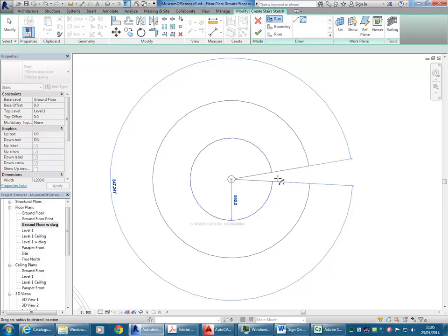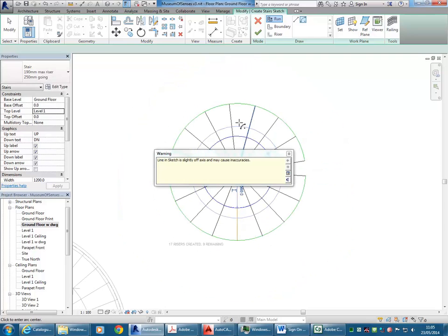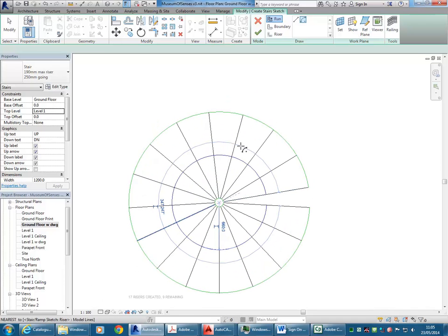Now, honestly, it's not something you should need to worry about. People often get to this point and think, oh my God, Revit's not going to do the stairs that I want to do. But you've got to think about what's possible, because if I go one more step, that's my 18th step, and that's the maximum I can have anyway. Yeah. And you need a landing. Yeah. And so if you're going on top of your stairs, a lot of older spiral stairs you'll see do that, but these days it's pretty difficult to do that without going over the limit. So just watch out for that, but otherwise spiral stairs, you can do pretty much anything you want.